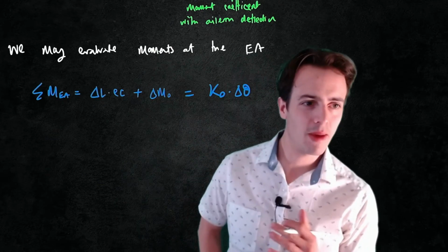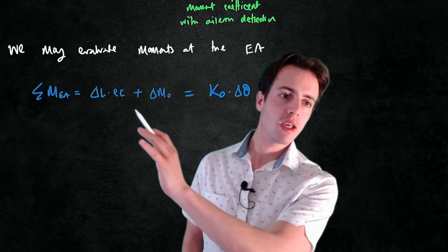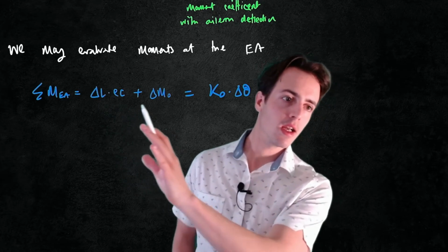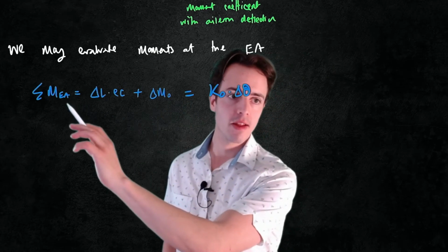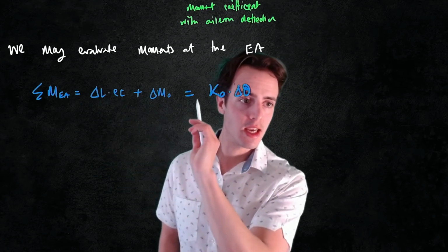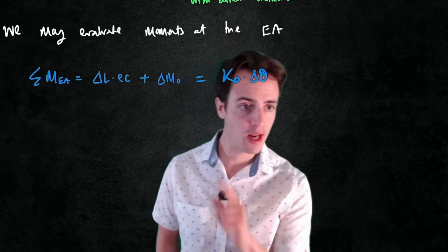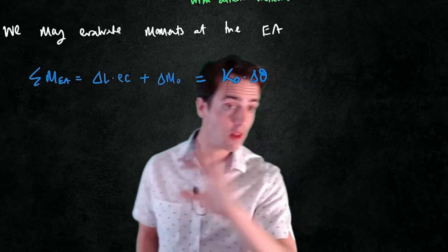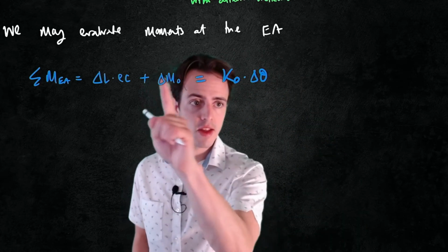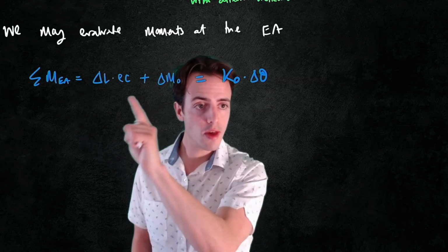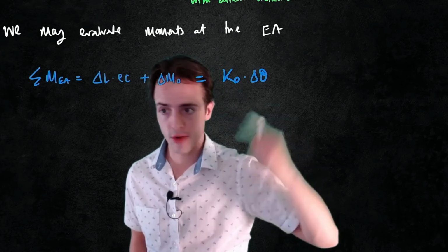I think mathematically I'm being slightly loose with some of my nomenclature here. This does work, but I've got to be careful because I'm not including in here the actual zero lift pitching moment. But let's pretend we've got an uncambered aerofoil and we're at zero incidence, that's fine. This whole development still works. So again, this is the moments due to the aileron deflection, and on this side we've got the torsional stiffness and the torsional deflection.